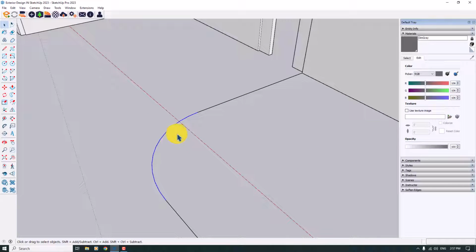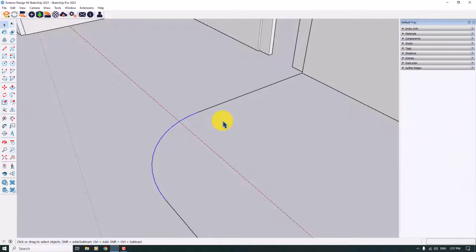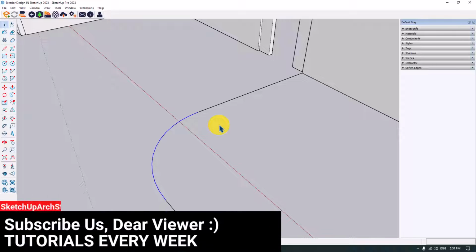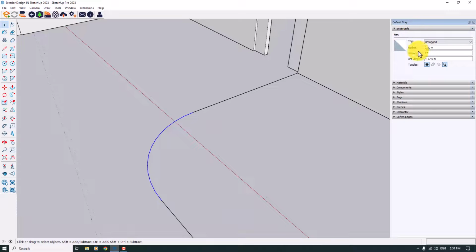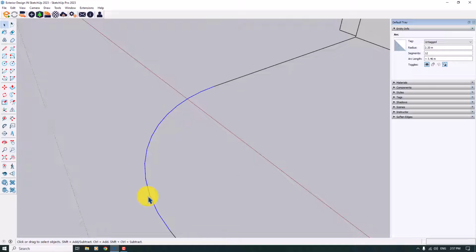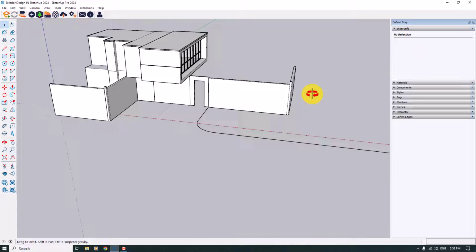Click on this fillet area here. In SketchUp, we only have segments, as opposed to other software like 3D Studio Max, where you use millions of polygons. In SketchUp, you have segments. So I will click on Entity Info. As you can see, it's not really smooth, so I will increase the segments from 12 to 24 in Entity Info. Everything is done for me right now.